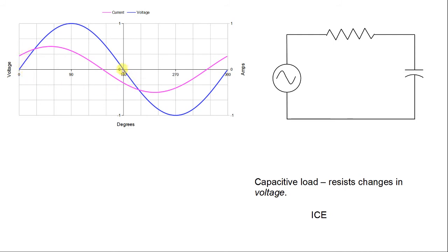They're not passing through 180, and they're not passing through 360 together, so they are out of phase. And I have done a 36-degree phase shift, but in this case I had to do a phase shift in the opposite direction. The current is leading the voltage here by 36 degrees. So now let's look at our volt-ampere waveform and see what problems this is going to cause for us.